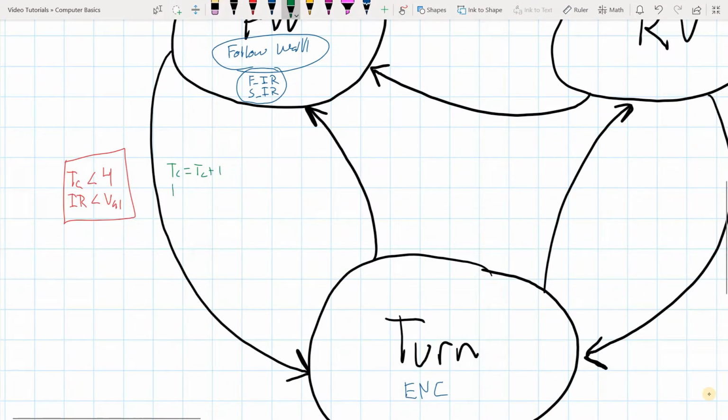and we are going to run our right wheel forward, and our left wheel in reverse. And there's one other thing that we're going to do. We also need to know when we've completed a turn, so we're going to get some encoder value. We're going to check to see where our encoder is, okay, something like that.